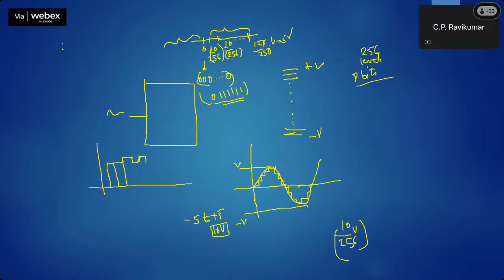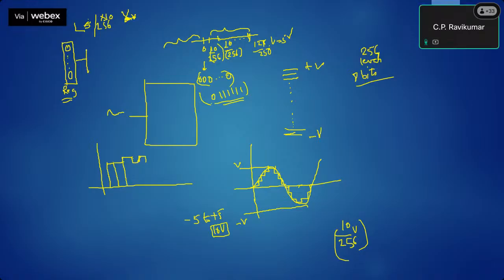So one way to do that would be, maybe we can start with a register which is loaded with, let us say, 0. And when I get an analog value, let us say it is 5 by 256th of a millivolt, 5 by 256 volts is what I get. So we will use some sort of a digital to analog converter. So inside the ADC, there is a DAC. Okay, this will convert this value to an analog value. In this case, it will say 0.